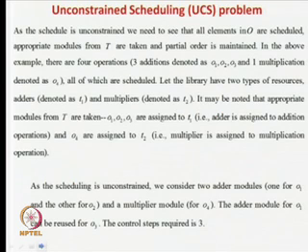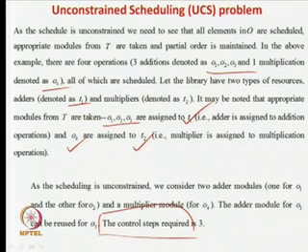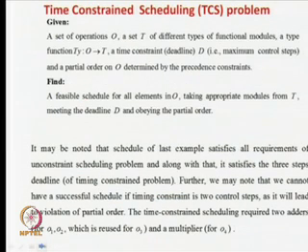Okay. So, whatever I discussed is written in this slide, that is 3 additions, O1 and O2 and O3, and 1 multiplication. We use T1 for the adders. So, O1, O2, O3 are all assigned to T1, O4 is assigned to T2, and then we define the time steps: O1, O2 in time step 1, O3 in time step 2 and O4 in time step 3. So, that is what has been done. We require 3 control steps and we require 2 adders and 1 multiplier module for this one. So, this is an unconstrained time schedule.